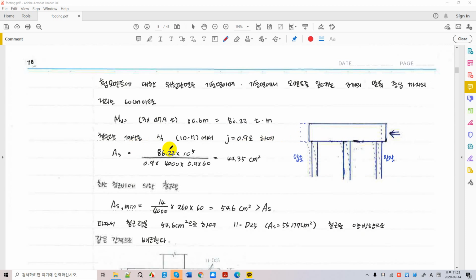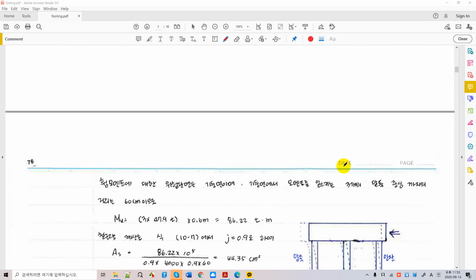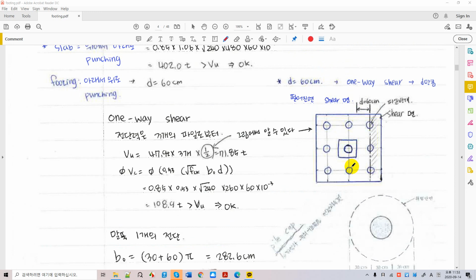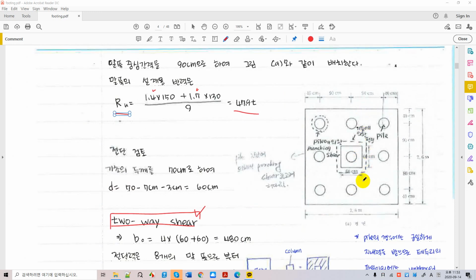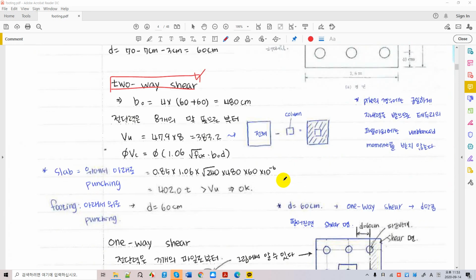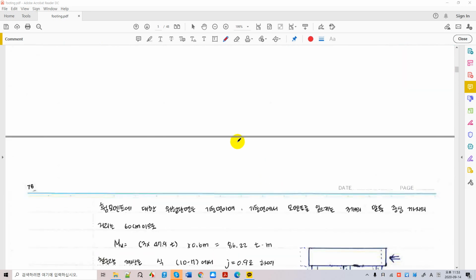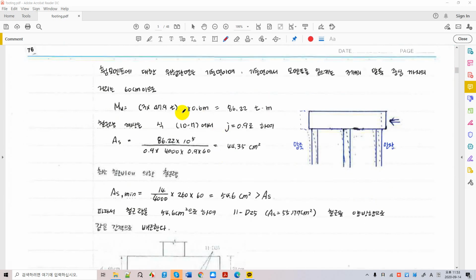That is simply 0.6 meter. Okay. So why don't you calculate to see if you can get 0.6 meter? I don't have to really worry about verifying this value for you, right? So we're going to use 0.6 without further verification, and it's easy: 3 times the pile force on each pile times the moment arm.